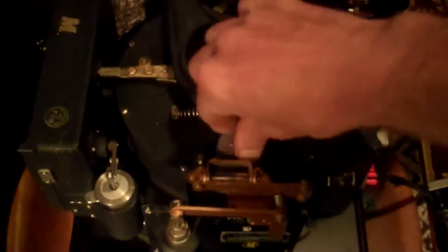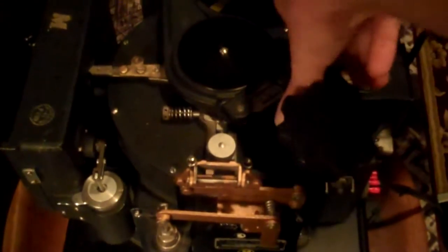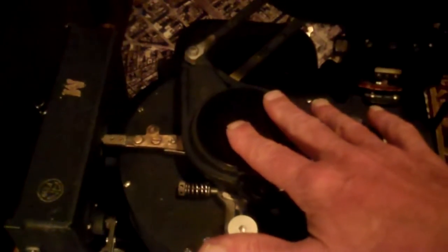During the later phases of the bomb run, the autopilot clutch is disengaged and the bomb sight clutch is engaged. This, along with the torque motor, allows the stabilizer gyro to now stabilize the sight head.